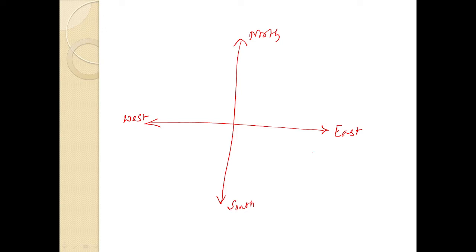Now every CAD software is going to follow some reference direction. Okay, so now this is 0 degree. Okay, this is 90 degree, 180 degree, 270 degree. So you can just observe here. In which direction is the angle specified? Whether angle is specified in clockwise or anti-clockwise? It is specified in anti-clockwise.